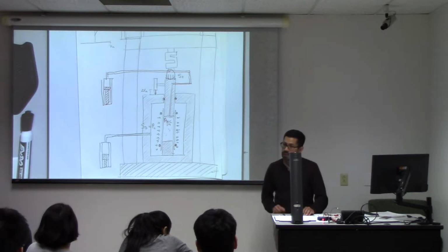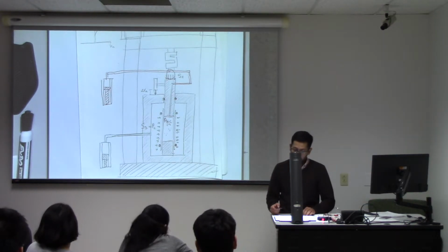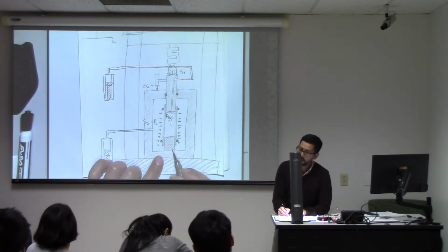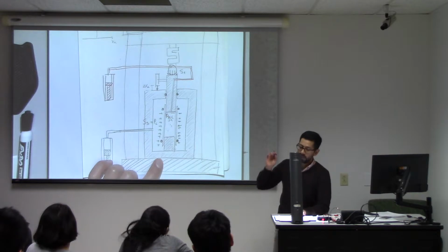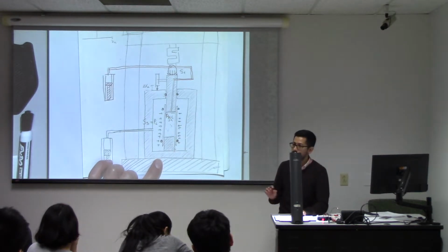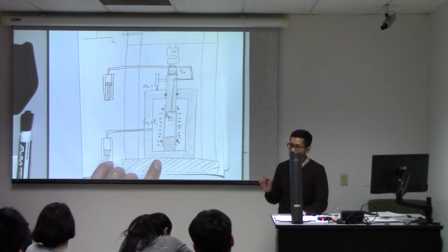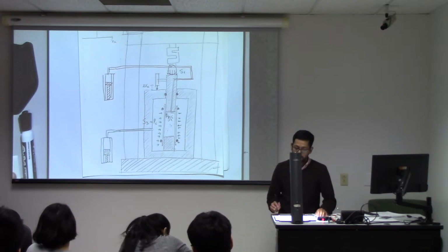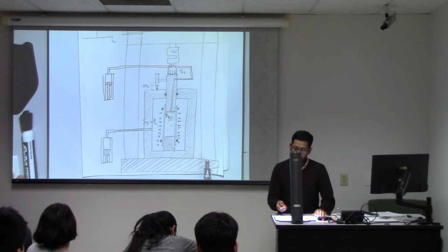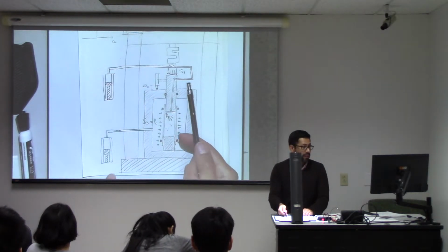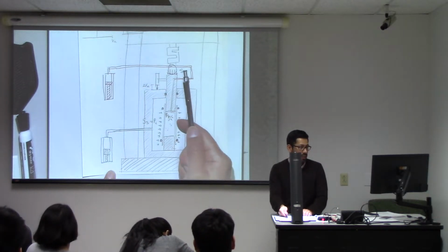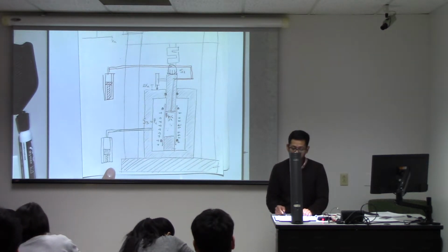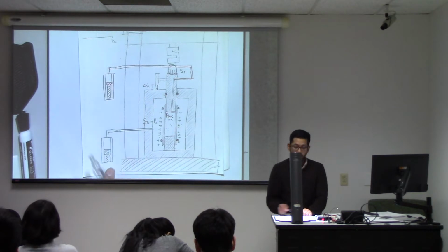There are some other machines, like the one we have in our lab, that have a load cell inside here. And that one measures effective stress, deviatoric stress. But in this case, as with the data that you have, you're going to measure total stresses. Notice this is the total stress that you measure here outside. This is the total stress that you measure in the pump. And this is the pressure that you measure in this other pump.